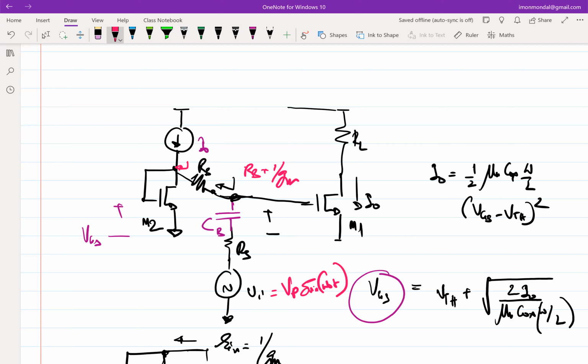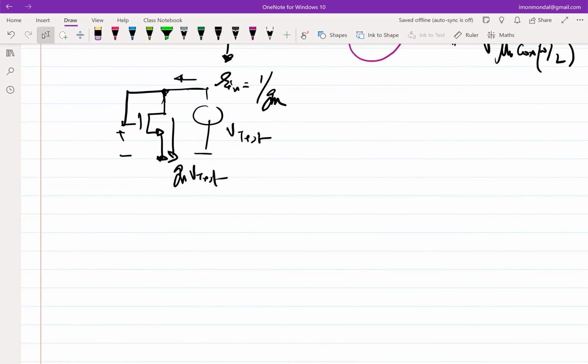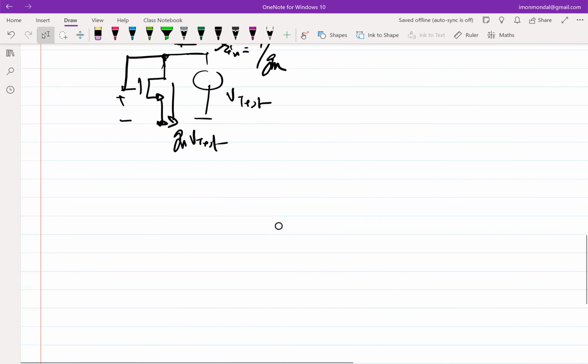Any questions? Now, threshold voltage variation is not the only variation which affects the current. Mobility is also a strong function of temperature, right? If temperature varies, mobility will also change. In a voltage biased transistor, I mean you have biased with a constant voltage between gate and source. So this is voltage bias, and this is current biased.